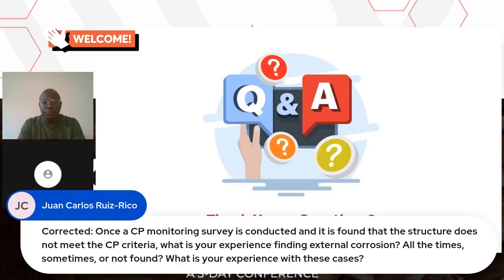Now, what I've noticed is that if you have a line immersed in water or wet soil, and those kinds of locations, you should try your best to work with that minus 850, because when it goes below minus 800, you start to have external corrosion. It may not be serious, but it starts to happen. So minus 850 is a criterion, but certain environments, in dry land, arid locations and the like, may not need minus 850. It may step down to minus 750. The ISO standard talks about resistivity measurements for various soils and protection criteria based on tests that have been done over the years for external corrosion.